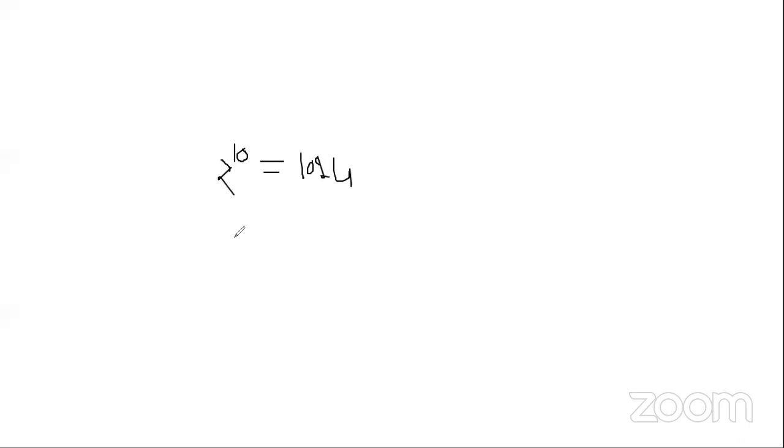So whenever we supply 0 volt to 5 volt to the Arduino, it will read in the format of 0 to 1023. 1023, because 0 is also counted in bit format. So 0 is also counted, 0 to 1023. The total number of values is 1024. Okay.